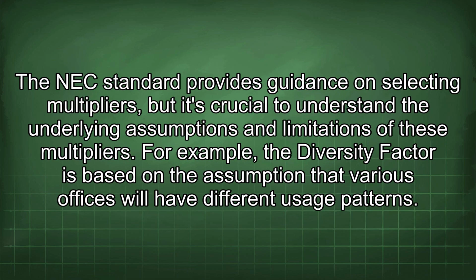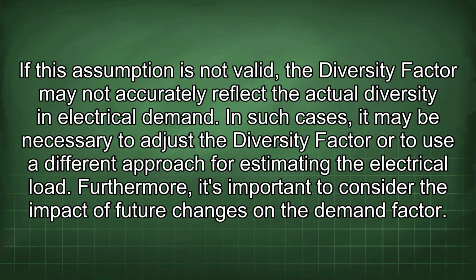The NEC standard provides guidance on selecting multipliers, but it's crucial to understand the underlying assumptions and limitations of these multipliers. For example, the diversity factor is based on the assumption that various offices will have different usage patterns. If this assumption is not valid, the diversity factor may not accurately reflect the actual diversity in electrical demand. In such cases, it may be necessary to adjust the diversity factor or to use a different approach for estimating